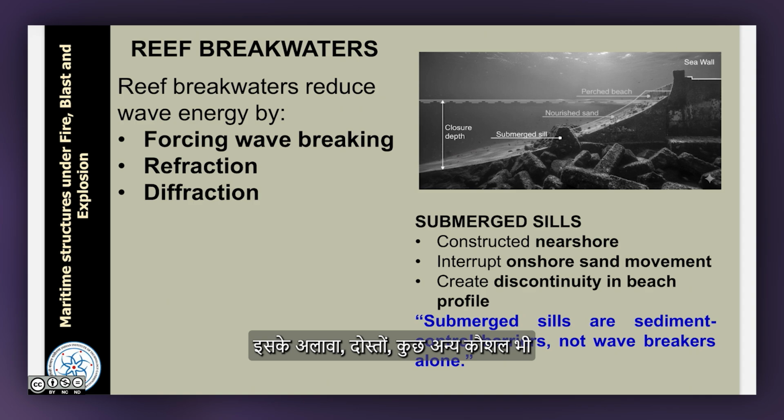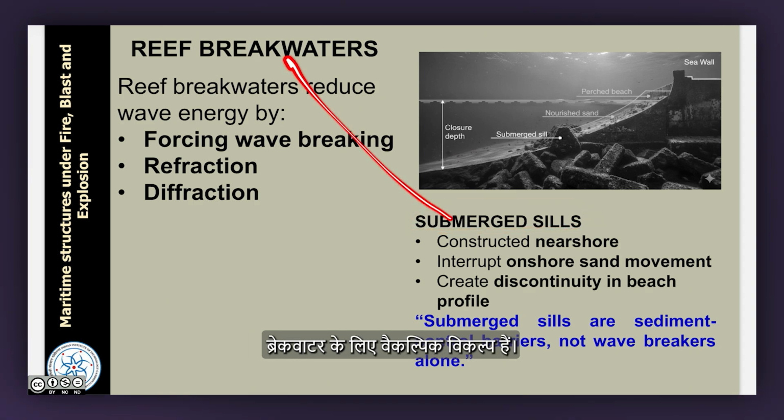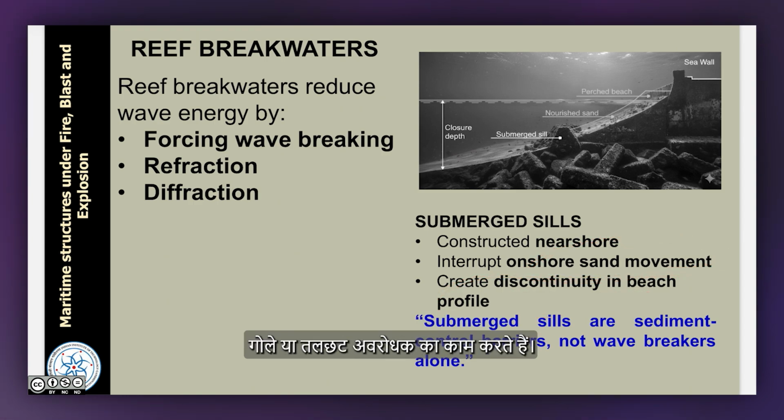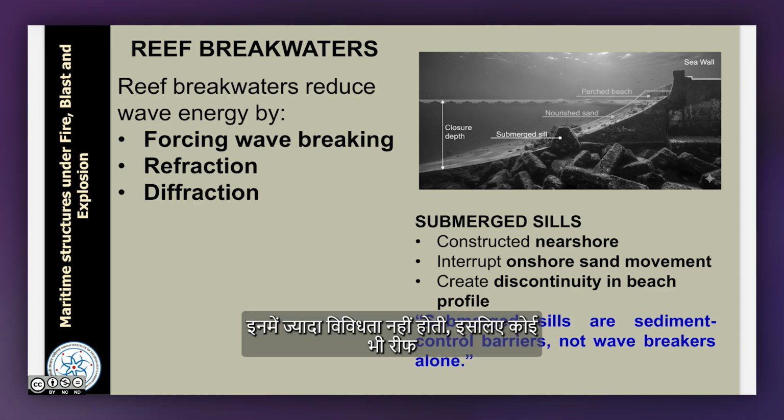Alternatively, friends, submerged sills are also alternatives to reef breakwaters. They are constructed near shore. They interrupt onshore sand movement and create discontinuity in the beach profile. Submerged sills are sediment control barriers. They are not wave barriers. So, one can quickly find the difference between a reef breakwater and submerged sills.